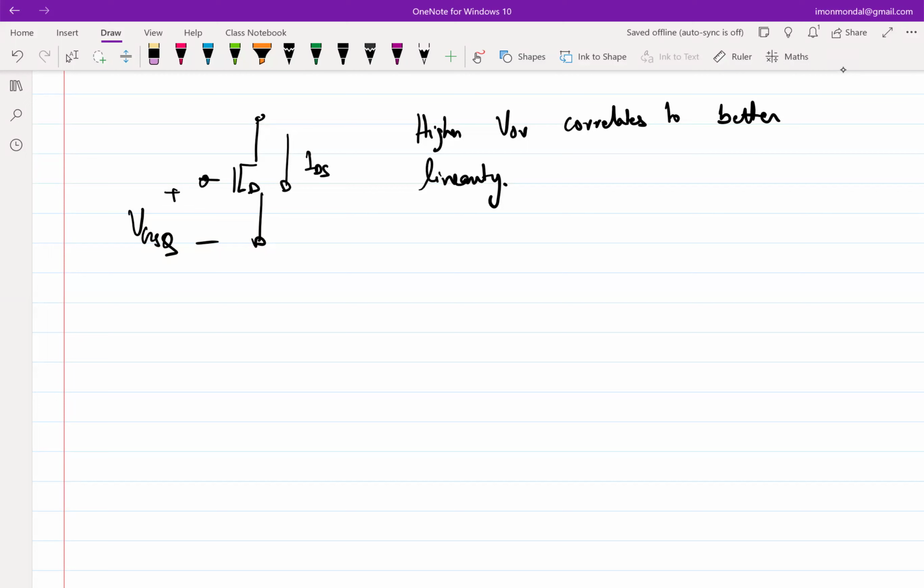It's because there is a velocity saturation that comes into the picture. When you typically derive the square law model, there is one condition for pinch off, and when you integrate, you get another condition, and both those get multiplied and you get the square. If you have velocity saturation, then those two conditions are not the same, so you don't get the square, you get the linear term. Now, if you simply go by the linear term, you might think that a transistor is a perfectly linear device, right? That also is not true. The truth is always between these extremes. It's neither fully linear nor square.